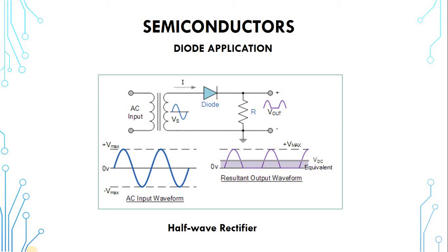If you look at the circuit as we have here, this is the diode, the circuit symbol of the diode. This side is the anode, this side the cathode. Like we concluded previously, the diode conducts in only one direction. Since the anode is more positive and the cathode is more negative, if you apply positive here and negative here, the diode conducts. But if you change the polarity, the diode will not conduct. So the diode conducts in only one direction, and in mechanical engineering it could be likened to the non-return valve.